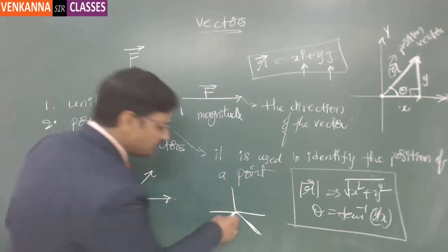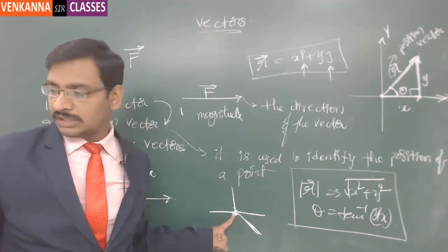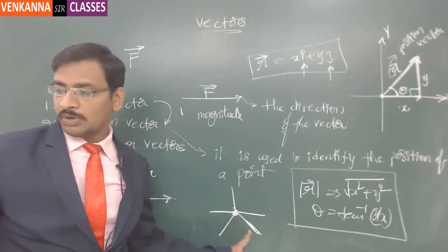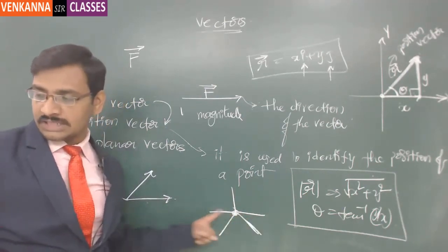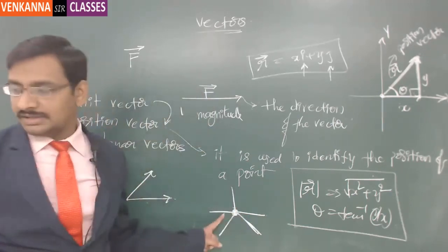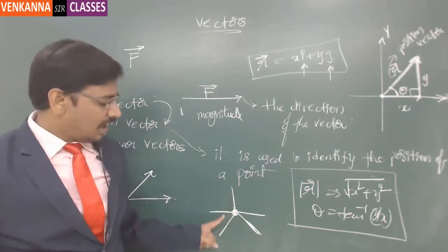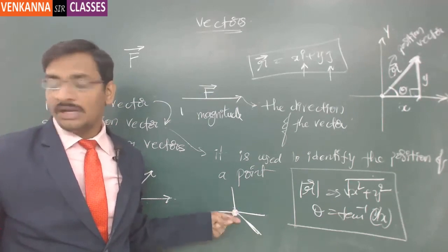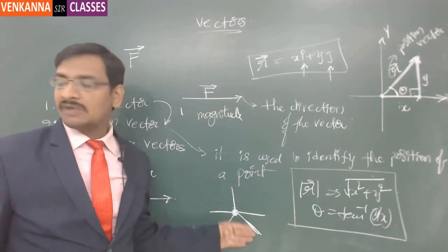Now at this particular point, all the forces are meeting together. Now there is one force acting from the top. These two are supporting pillars, and these are transmitting to the next trusses. Now whatever force we calculated here has to be under equilibrium condition, which essentially means that all the forces together make a resultant of zero. Now the analysis we are going to deal with here is all coplanar vectors.